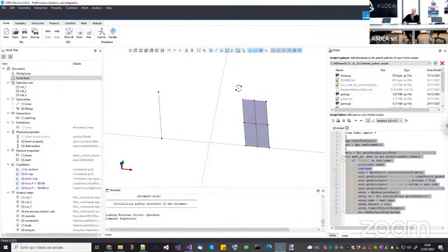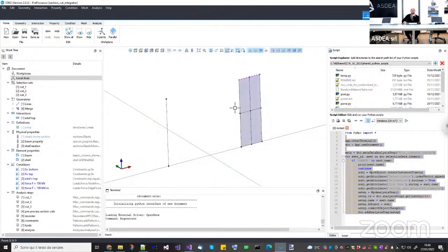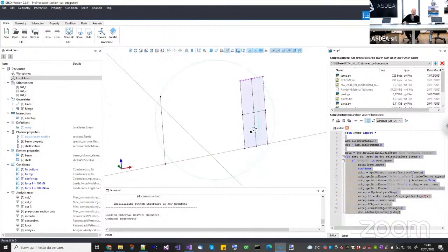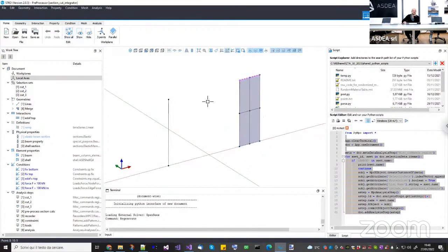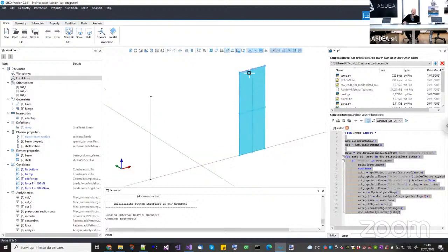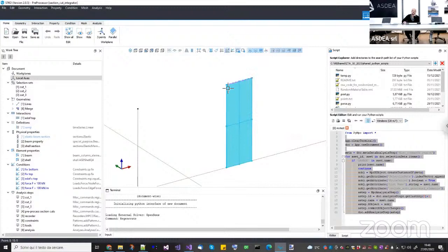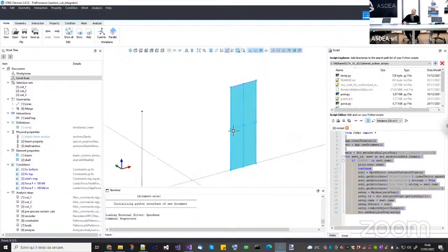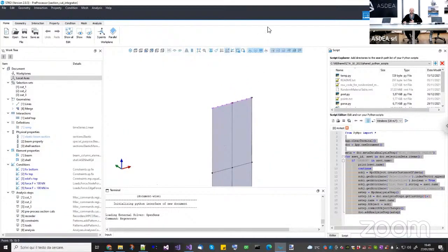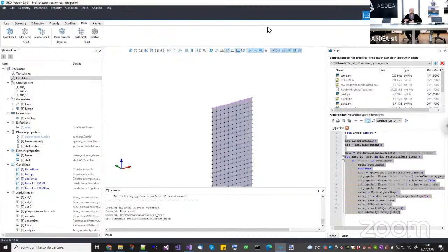The idea of Valentina was, always in the frame of modeling a wall, either with a beam or with soil, it can be nice to have a section cut integrator. So for example, you have a beam modeled with shell elements, then you create a cut here, or a cut in the middle or at the bottom. And I'm creating a script to integrate all the elements and forces along the cut to basically have this kind of integral. So let me show you what the script will do.